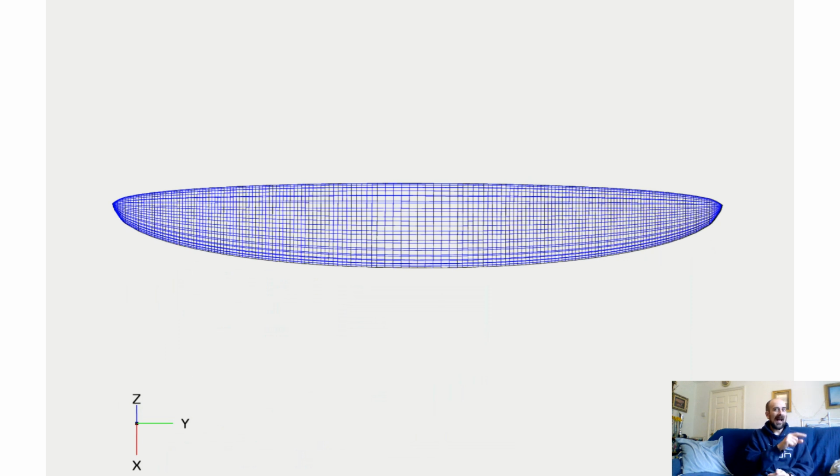In principle, for any planform of wing, so for any shape wing, you could still get an elliptical lift distribution for it by adjusting the angle of each section of the wing. So we talk about the twist or the washout along the wing, so how does that wing twist along its length, and also by changing the section as you go along it. If you do that, then you can effectively correct for the non-ellipticalness of the shape of the wing, so that you still get a perfect lift distribution.